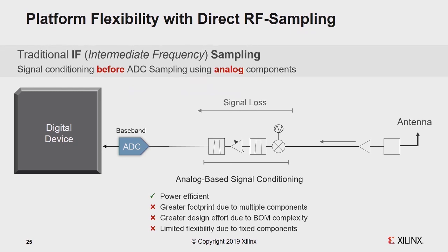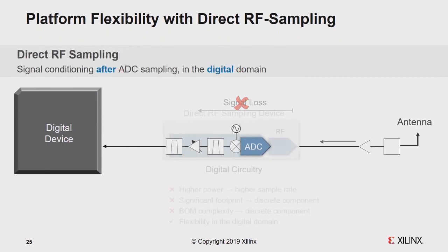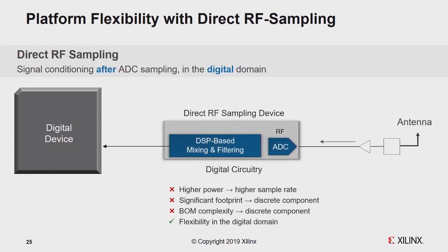Next, the analog data converter IC vendors introduced the RF direct data converter. The signal comes directly from the antenna and is sampled directly by the ADC, and all the down converting, like the NCO and decimation, is put behind the ADC.